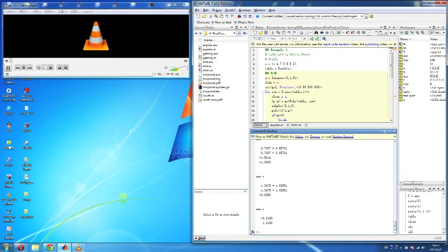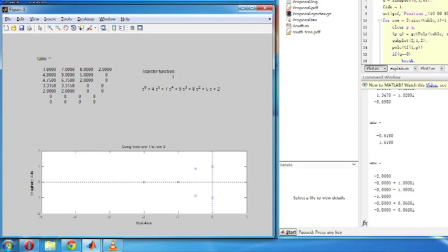In this video, I will show intuitively why Routh-Hurwitz works. First, let's look at the following example. Here, the characteristic equation has roots at -2, -1, plus or minus j, and 1/2 plus or minus √3 over 2j. This is a marginally stable system.